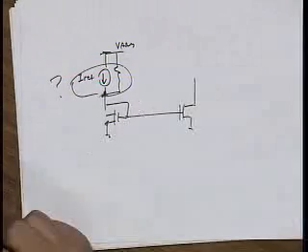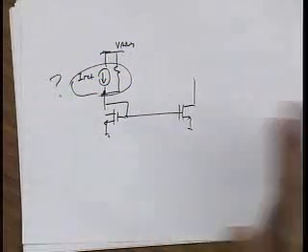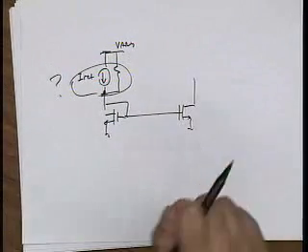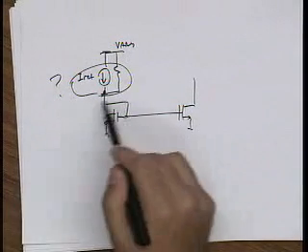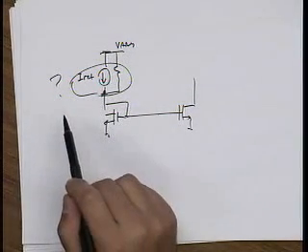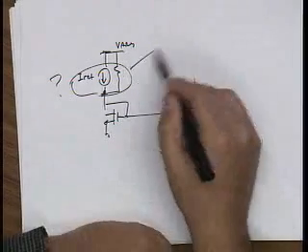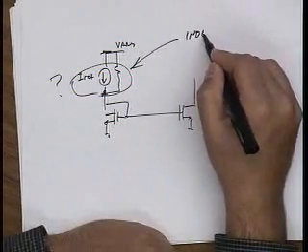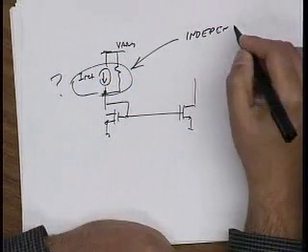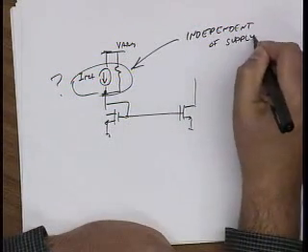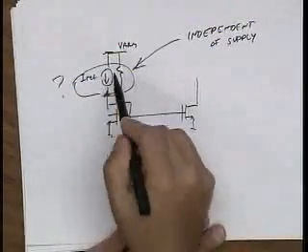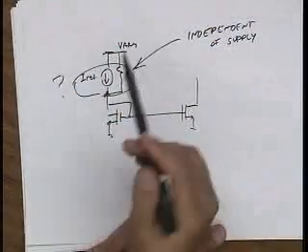But of course, if you're designing something where there's going to be a million copies of it, you're not going to have someone tweaking a resistor a million times. So we need to design a reference. In particular, we want this reference to be hopefully independent of supply. In other words, the supply voltage varies for many reasons, right?